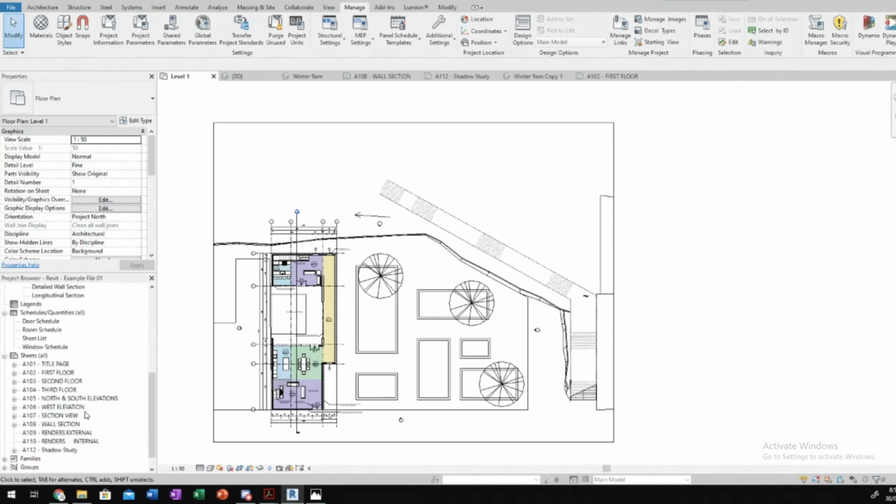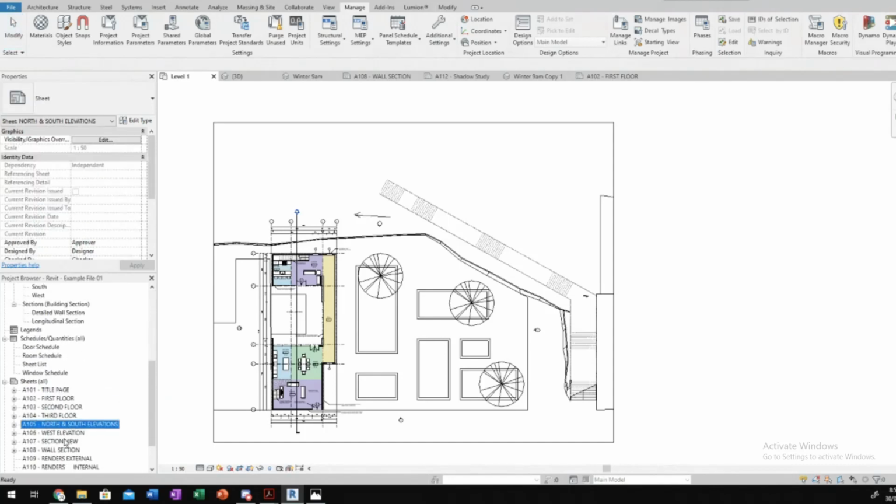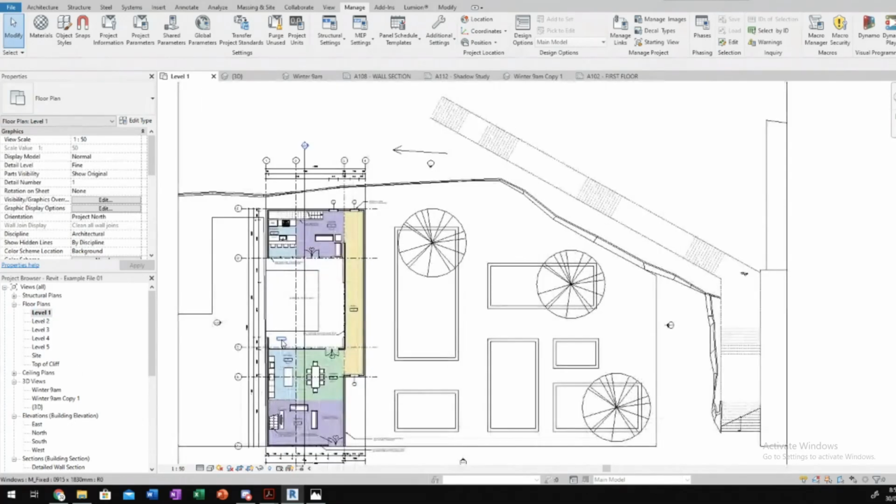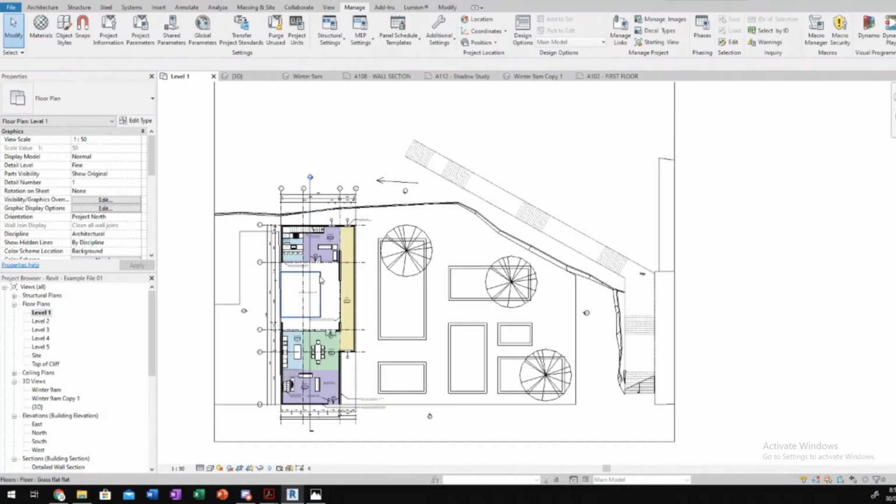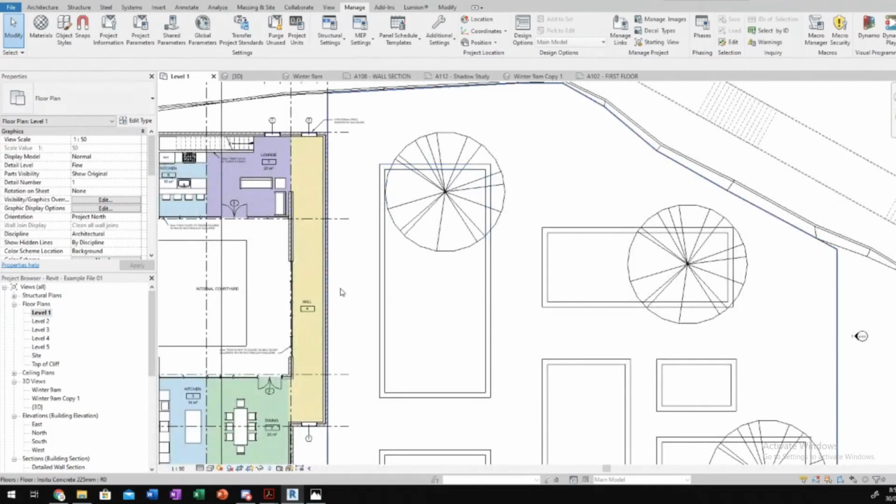So yeah, just make sure whenever you're setting up, set up all your sheets here. So add your sheets, name them, make them an A3 if you need it for an A3 document. You can change all of that. But yeah, so that's just stuff to be careful about. Cool. Now, I wanted to go over a couple of basic modeling that you guys were asking about in terms of walls, stuff like that.